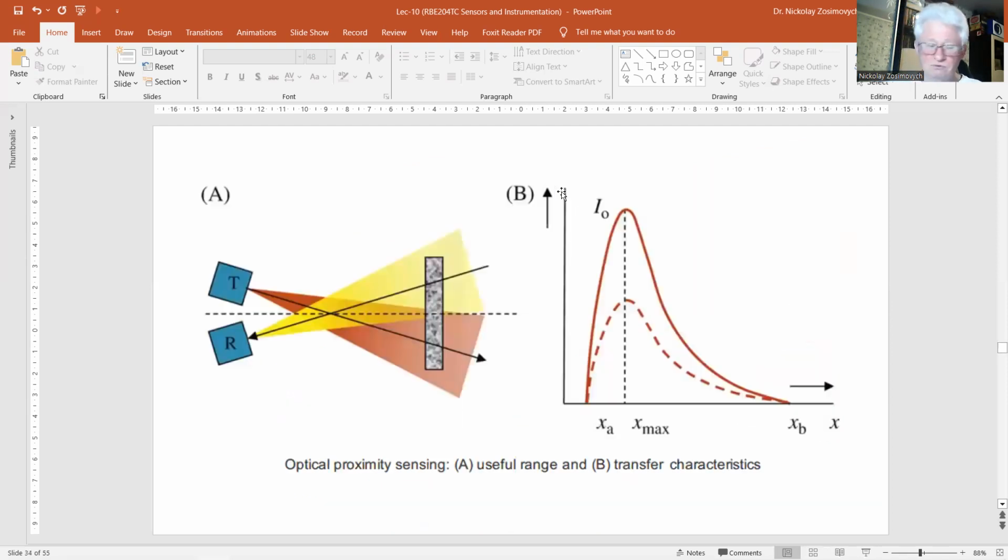And this figure 2. With 2 receiving fibers in differential mode, most common mode interference, for instance, the intensity of the emitter, is subtracted. The sensitivity characteristic depends on the angle of divergence, the standoff distance, and the angles between the fiber ends and the flat target. Since the output is an analog signal, the resolution of the distance measurement is mainly noise limited.